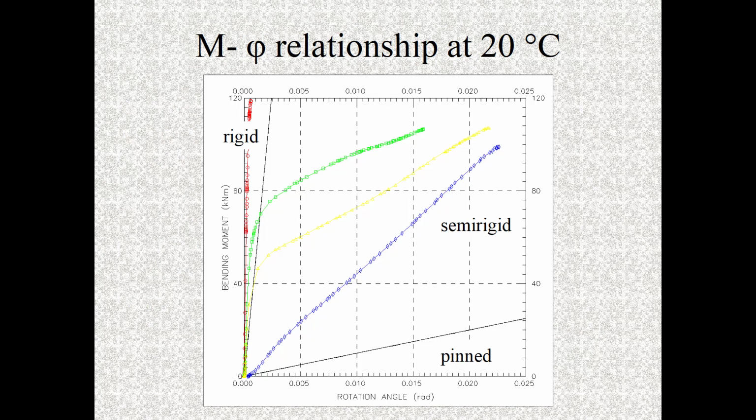According to the rules prescribed by Eurocode 1993-1-8, the joint fitted with 20 mm end plate behaves as rigid within the whole scope of this loading program. The joints fitted with 10 and 8 mm end plate follow this behavior up to about 50% of their total bearing capacity and later on change to semi-rigid behavior, while the remaining joint fitted with 6 mm end plate from the beginning behaves as semi-rigid.